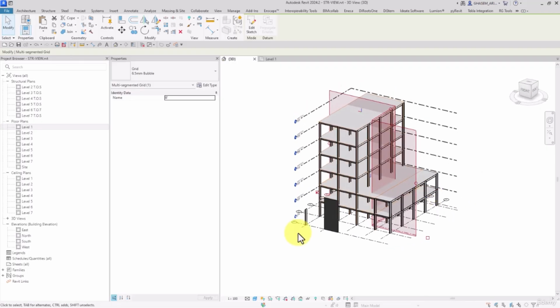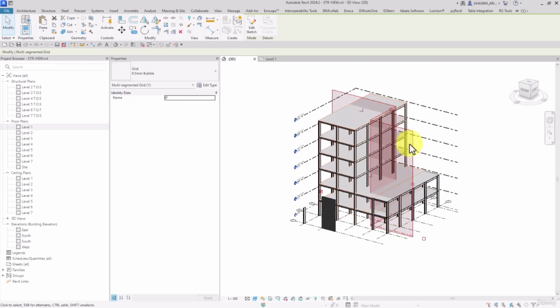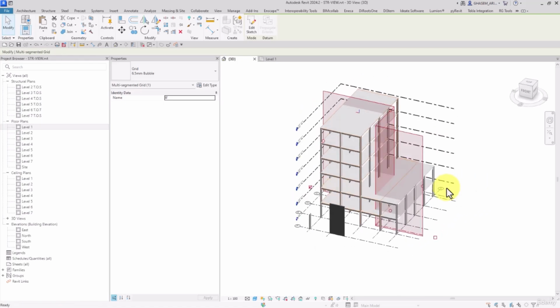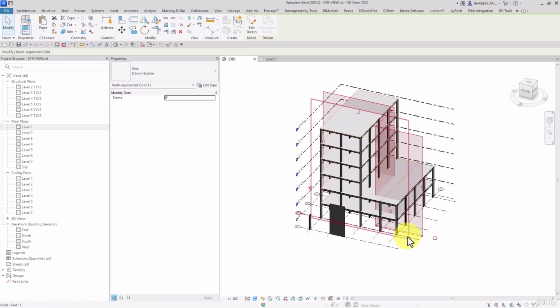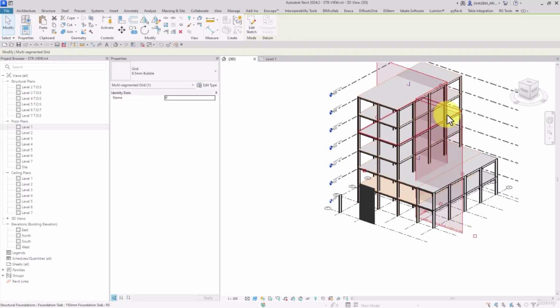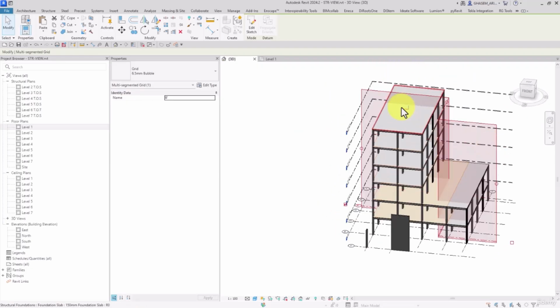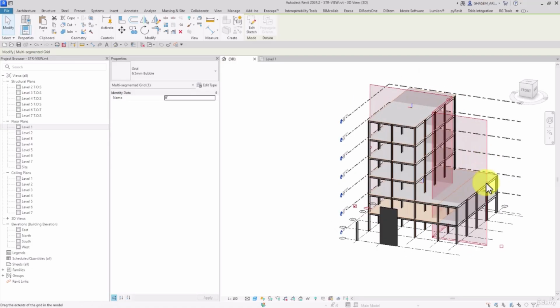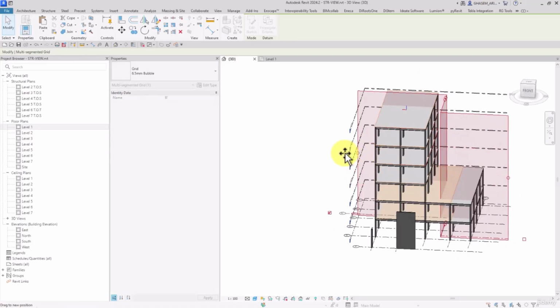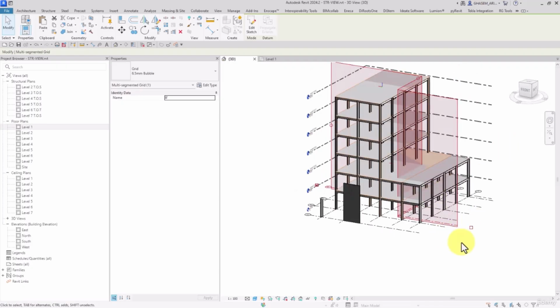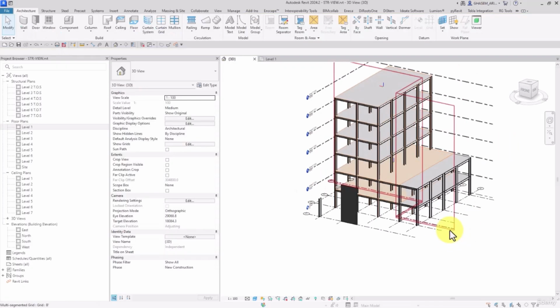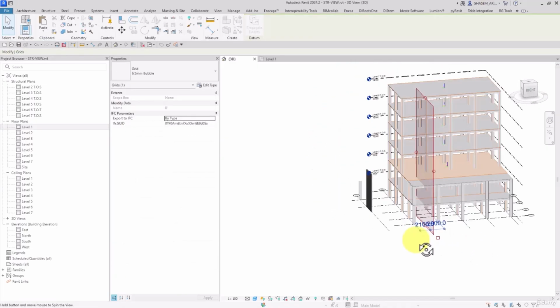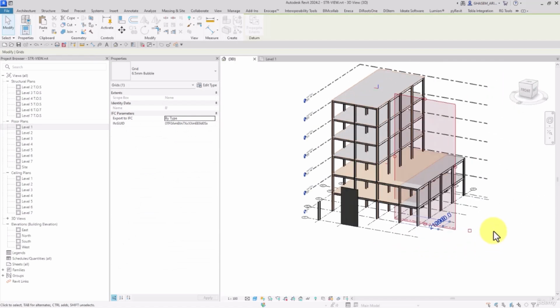When we draw a multi-segment grid, as you can see, when we select it, we select them unitedly. And after selecting it, we can edit it, we can resize it, change the height, width, and others. And the point here is that we can hold the cursor on the segments. Each of the segments, here we got 3 segments. If I press down the tab, we can select the segments individually, okay?